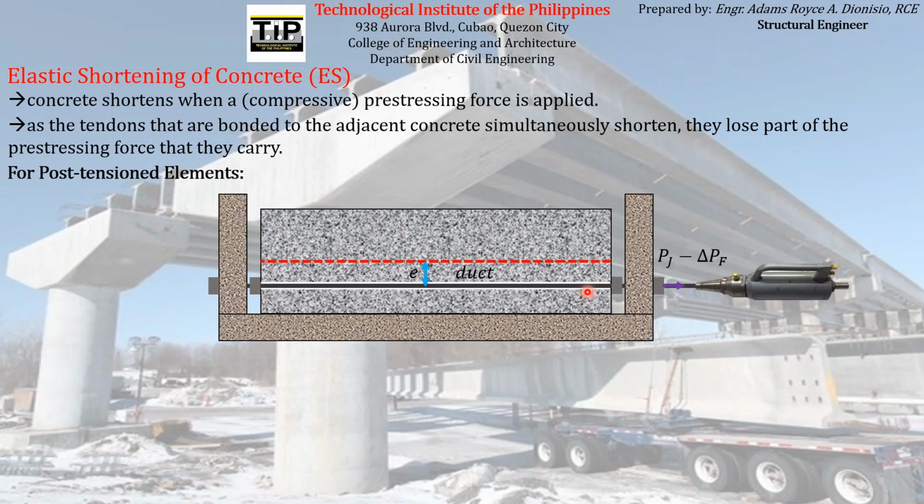So again, after the pre-stressing reinforcement is jacked, it will be cut, thereby transferring the pre-stressing force that it carries to the concrete element.